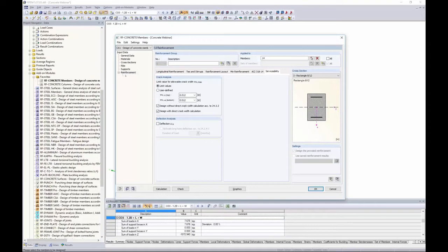So how exactly do we determine what the crack width is? What's interesting is that the ACI does not give you an exact equation for how to calculate crack width. Basically in chapter 24, it tells you to limit the longitudinal spacing so that you can decrease your crack width, and that comes from exactly this section in the ACI. So when you have this checked, the program will limit your spacing based on this criteria. Now, if you're looking for more of a comparison to an actual crack width, then we need to turn to some equations that are more theoretical. Again, they're not found in the code. So in our program, we refer to the Gergely-Lutz equation. What this will do is calculate an actual width of your crack based on all of your loading and your criteria and such. So that's what this is about with our checkbox here.